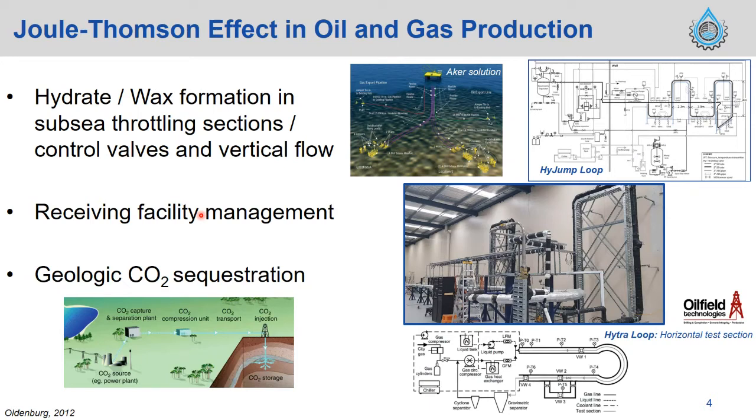This also applies to receiving facilities, so it's also important for facility management. Furthermore, it could be of interest for CO2 sequestration. When we inject CO2 underground, with the JT cooling the pores can be blocked, which will prevent CO2 storage in the ground.